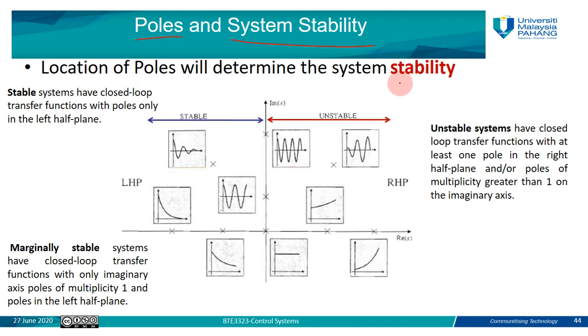So based on what we said, our transfer function, for example, G(s), is equal to the output C(s) over the input, which is R(s), correct? So this can have some values for the output, for example, s plus 2, over s squared plus s plus 3, and so on.